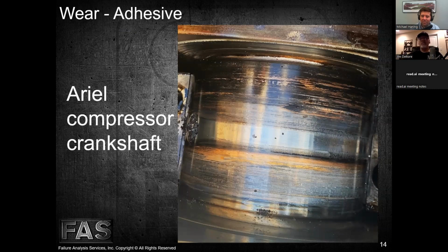So just so guys understand that at this point here, a few things have happened to that crankshaft because of the heat and load that's been generated and excessive clearances. The crankshaft is most likely bent. The crankshaft also most likely has taper wear on it now because we've taken steel material off as well as bonded bearing material to it, and the surface finish is extremely rough where it needs to be extremely smooth if we're going to put it against a new bearing.